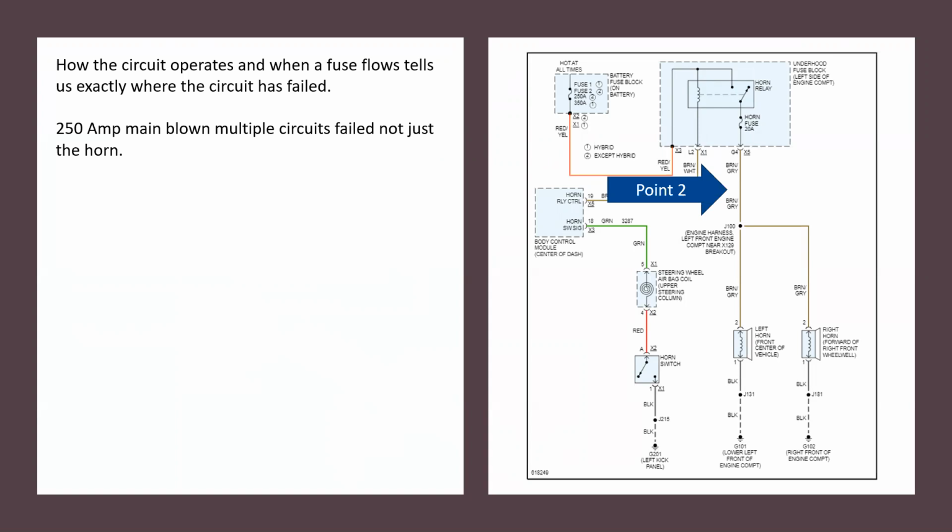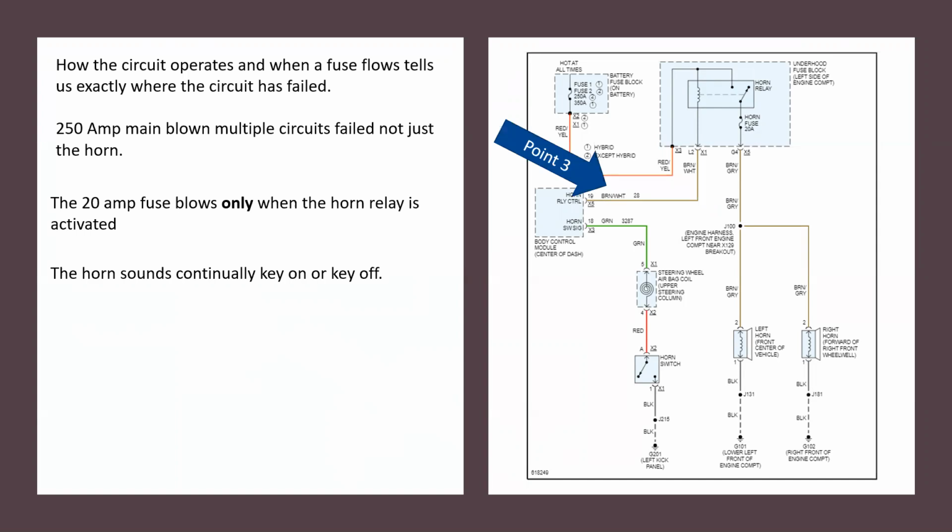So as soon as I put my hand on the horn button, I'd close the switch inside the relay. It'd blow the 20 amp fuse, and again, the horns wouldn't sound. So the fuse is only blowing when the horn relay is activated.